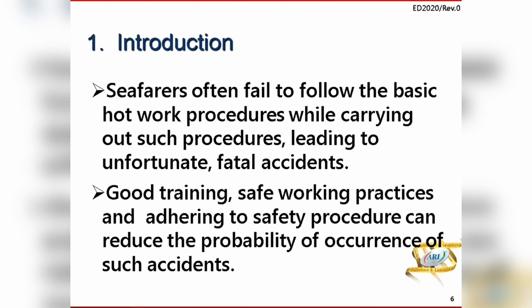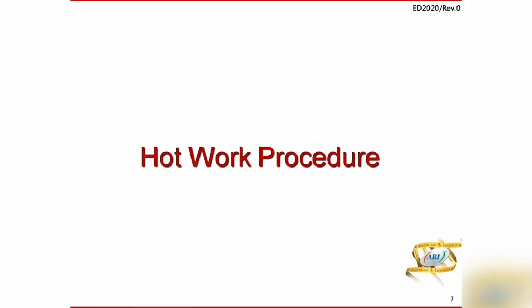Seafarers often fail to follow the basic hot work procedure when carrying out these jobs, leading to unfortunate accidents which are fatal. So you require good training, safe working practices, and you have to adhere to safety procedures so that the probability of occurrence of accidents is reduced.